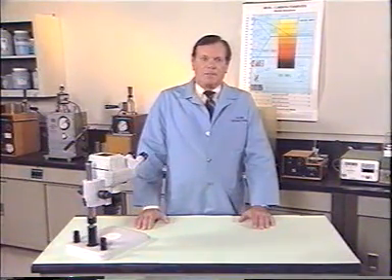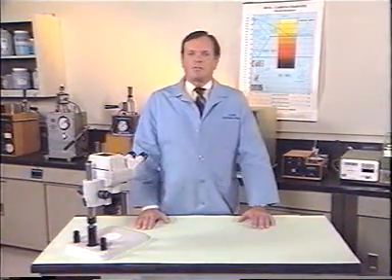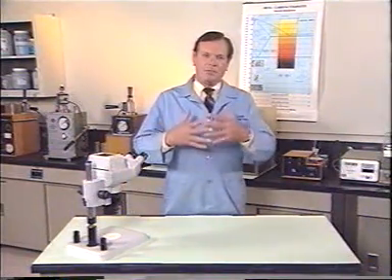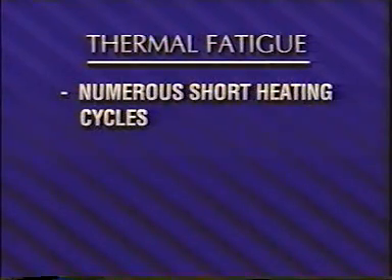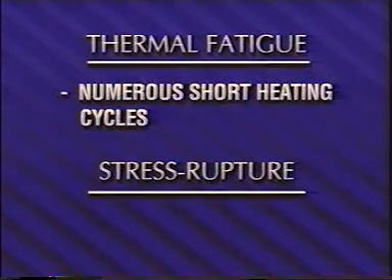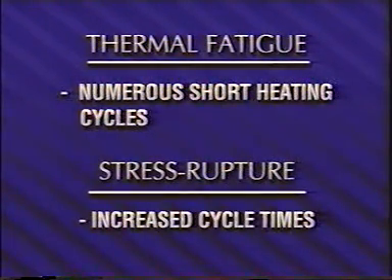Under certain circumstances, thermal fatigue and stress rupture failures blend into each other. Thermal fatigue is the basic mechanism in failures caused by numerous short heating and cooling cycles. Stress rupture becomes important as the cycle times increase. Stress rupture, therefore, is primarily a long-term rate process.